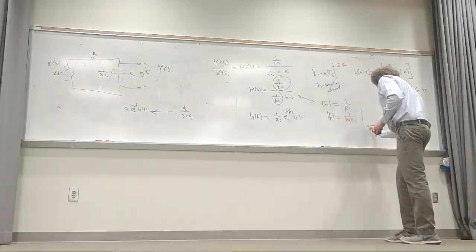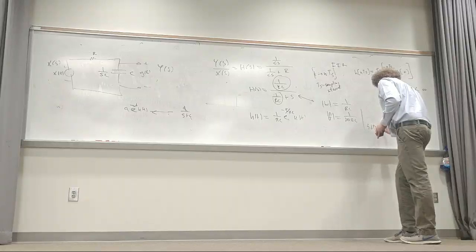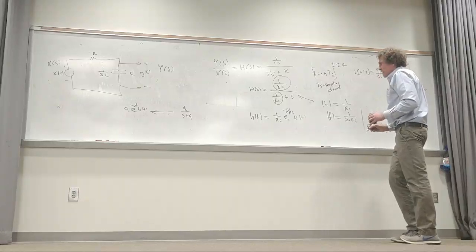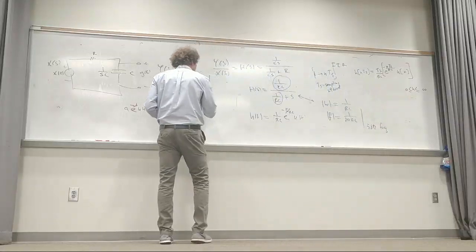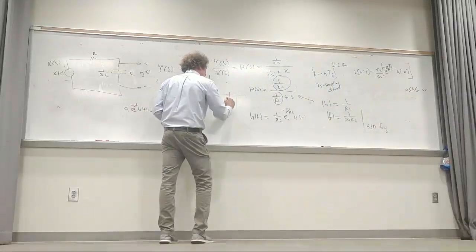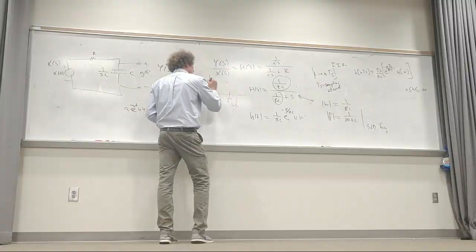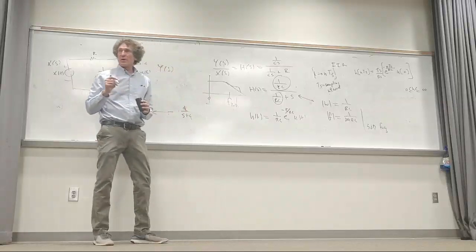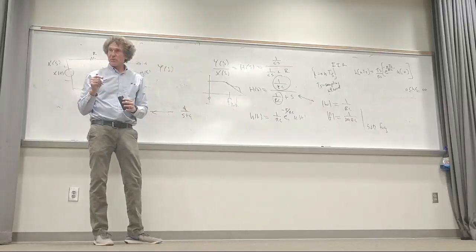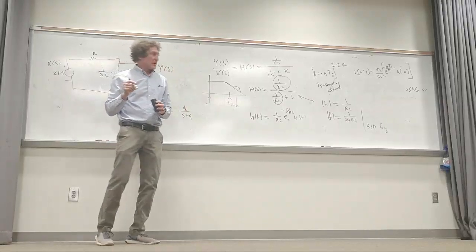And this would be the 3 dB frequency, right here. So if you're plotting the filter output from 0 to F 3 dB right there, that's where it starts coming down, and then from then on, you're getting 20 dB per decade of roll-off, if you did a Bode plot on that.